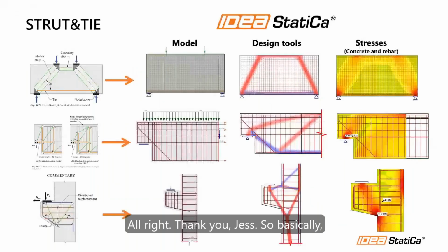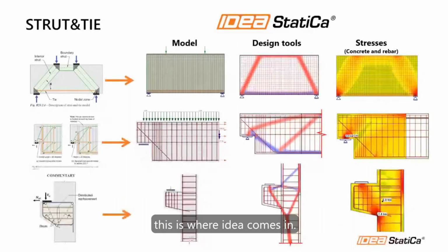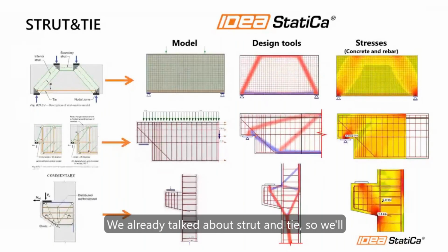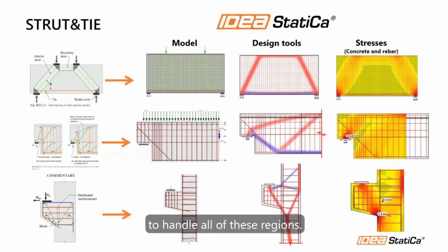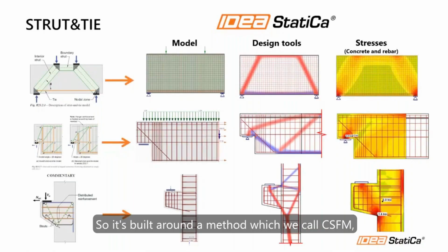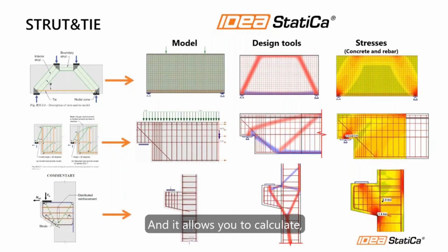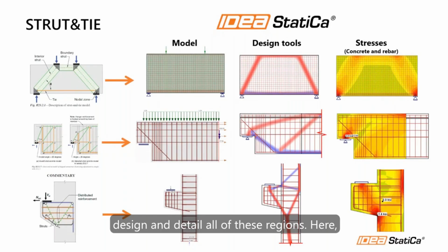Alrighty, thank you, Jess. So basically, this is where IDEA comes in. We already talked about strut and tie, so we'll see where IDEA plays into this role. So in IDEA StatiCa, we developed a software solution that's specifically able to handle all of these regions. It's built around a method which we call CSFM, which is basically the compatible stress field method, and it allows you to calculate, design, and detail all of these key regions.